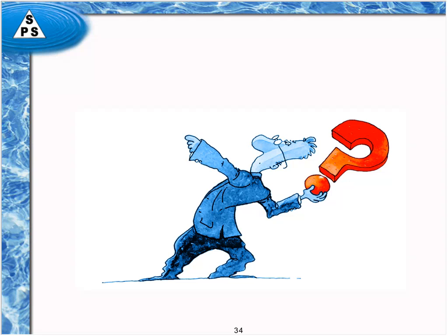In fact, most systems that are being put in to this day have hot water sanitizable systems. There are still some cold or ambient systems being put in because not everybody has heat sources available to be able to heat a system like that. But it's very typical for just about any vendor who could put in a water system to be able to put in a hot water sanitizable system.